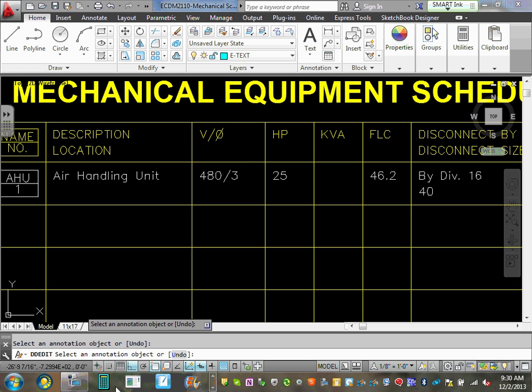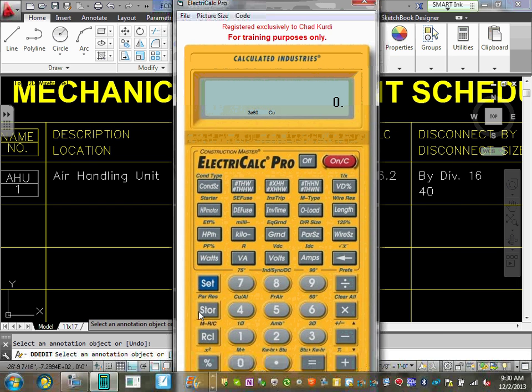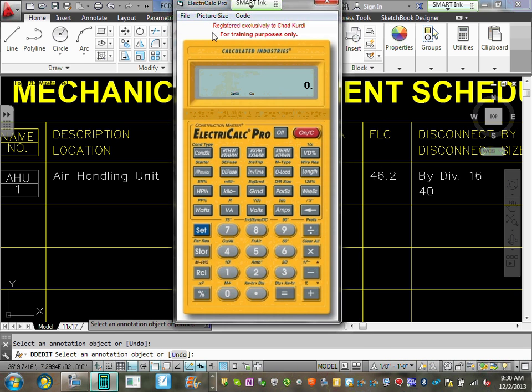I have to use the calculator for the ease of, here's my calculator, except if you guys have your calculator, you can follow with me very easily. So make sure your calculation is set at 75. Now it's set at three-phase 75. I have a 208 voltage system. Here's my 208 volt. It's a 15 horsepower. Here's my 15. Here's my horsepower. My full load amp is 46.2. Cool?